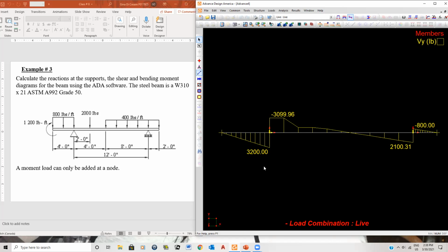And like I said, when you draw it, guys, just draw it like this, and then just give me the values, and that's it. That's all I want to see. I want to be able to see that you know how to extrapolate the information you need to actually design this beam, if these were the results you're going to be designing the beam for. You understand? For shear and for bending moment.